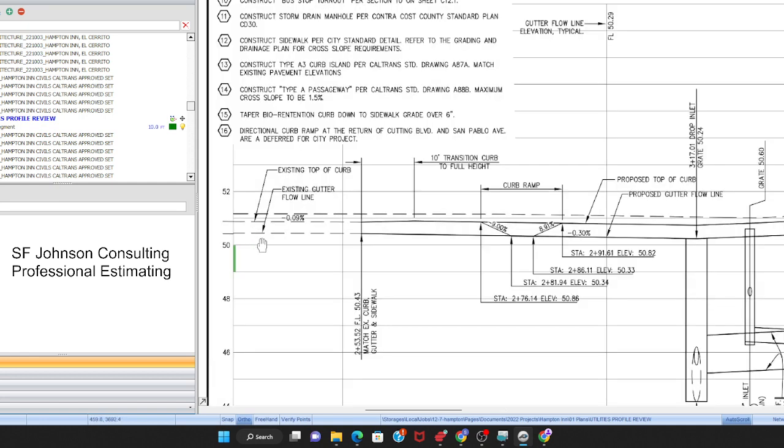Okay, and so because remember that's your existing, this is the elevation of the ramp, starts from here to here. So really your new work is starting here. This is all existing. This is all new work. And so, in terms of your dirt, right, we're looking at a section view of the earth, the elevation. This is existing. You got to cut all that out to get down here. Because this is where you need to really start the new curb. Gutter. Gutter starts here, down here. So you have to cut out from here to where the gutter starts.